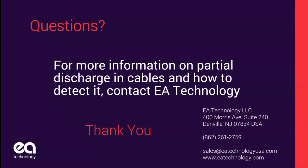Could you please talk more about the safety concern when using the RFCT? Sure. So RFCTs, we're attaching them to the ground, and you would think that is 100% safe, but there are a couple of considerations you need to worry about. One is the ground strap itself cannot part. The highest fault current that might occur through the shield cannot be more than that cable can carry.